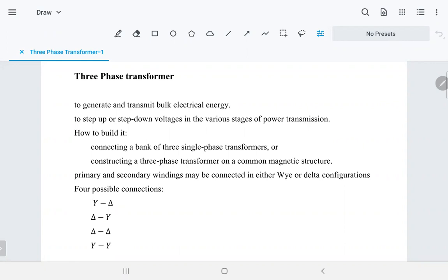And that's why when we do the equivalent circuit for a three-phase transformer, usually we ignore the resistance and only concern ourselves with the reactance, because you know the Z equivalent of the transformer is R equivalent plus jX equivalent. We just make R zero. It's not zero, but compared to X it's nothing, because it's thick wire, so the resistance is really nothing. But the reactance is more effective.